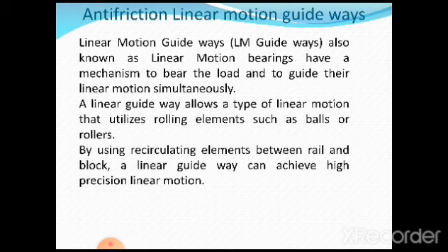They have a mechanism to bear the load and to guide the linear motion simultaneously, so there are two capacities. The LM guideways are designed in such a way that between the stationary element and the moving element, either the balls or the rollers are inserted, and the moving element is made to move very smoothly without any difficulty,